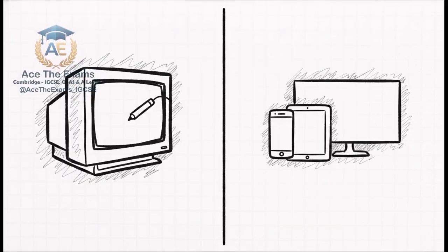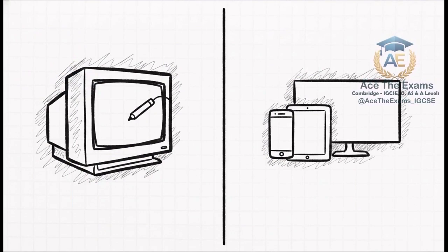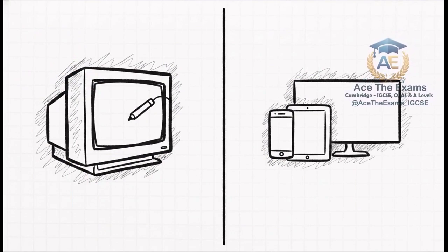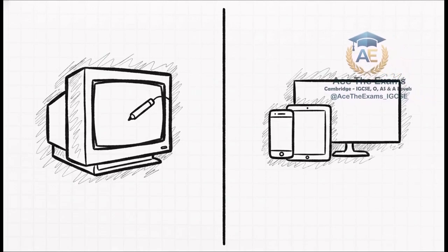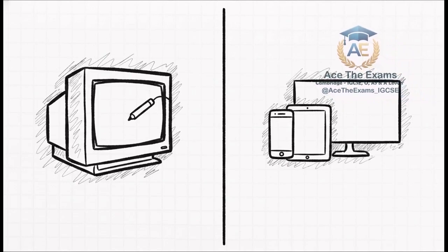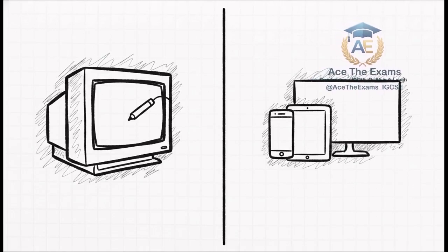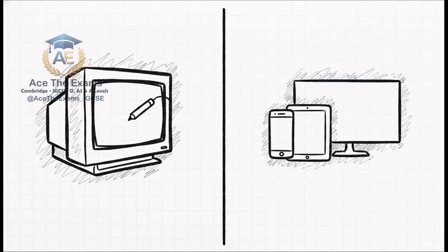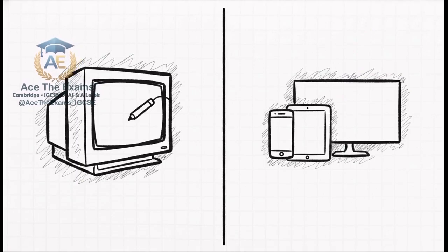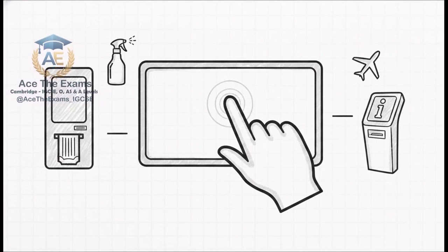And this brilliantly illustrates exactly what examiners want to see. Just look at the contrast here. If you're hit with a question about an old CAD system using a light pen, boom, CRT is your answer, even though it's heavy, gets hot, and flickers. But for practically everything else today, tablets, smartphones, laptops, LCDs and LEDs are the undisputed standard. Why? Because they're lightweight, they use low power, and there's zero flicker. You do need to remember the trade-offs though. LCDs need that backlighting, which can sometimes cause uneven illumination, while true LEDs offer amazing contrast, but yeah, they're definitely more expensive.